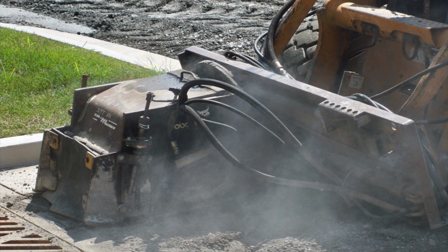You have the utilities here. You can see where he's cutting in the corner. DI sitting right here. Curb and gutter left and right of him. It takes a little bit more time, but all that material is then pulled away from that curb line and pulled away from the utility. The reclaimer will come through and pulverize all that material and blend it all together, making it a homogeneous mix. That's the whole intent. And that material is then graded back and compacted properly.